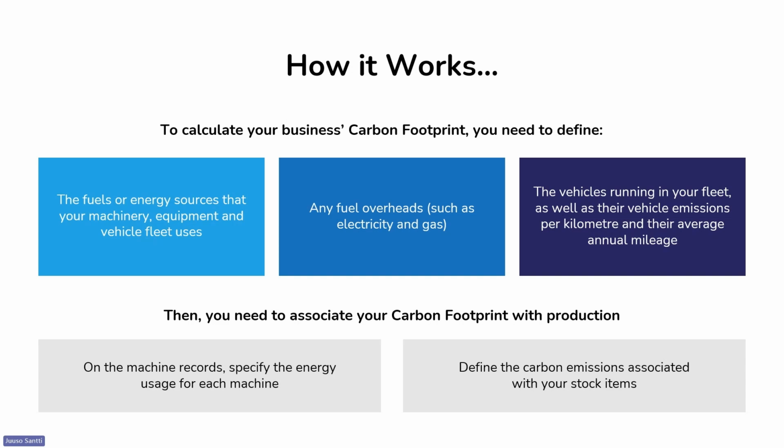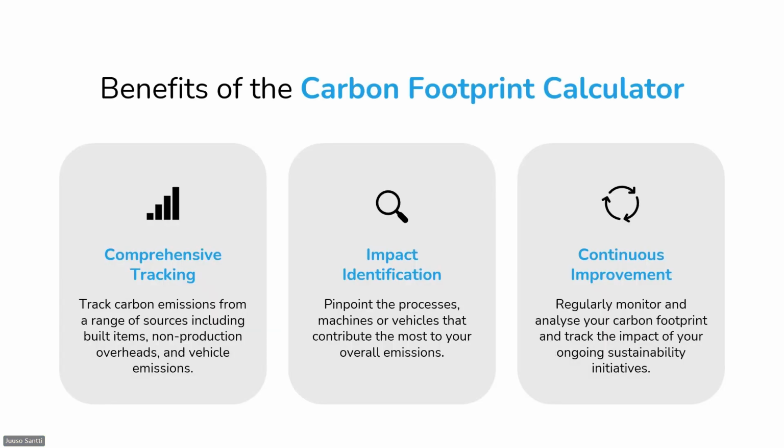Booking time for the machines will give you the actual carbon cost of energy used in manufacturing processes, but you don't necessarily have to report the actuals. You can base those calculations off your electricity bill as well. Combined with the kilograms of CO2 equivalent cost of the components, this will give you the total carbon cost of your finished items.